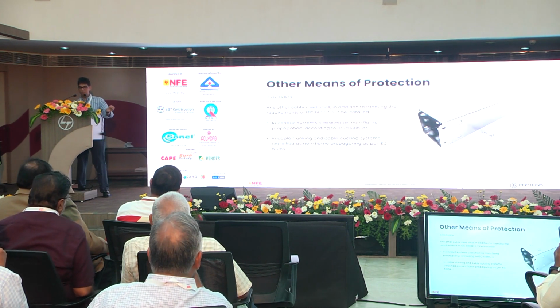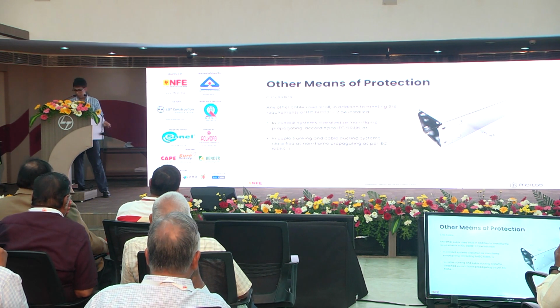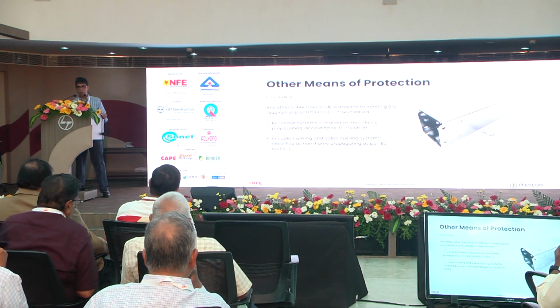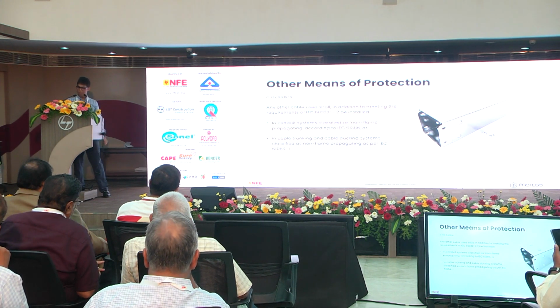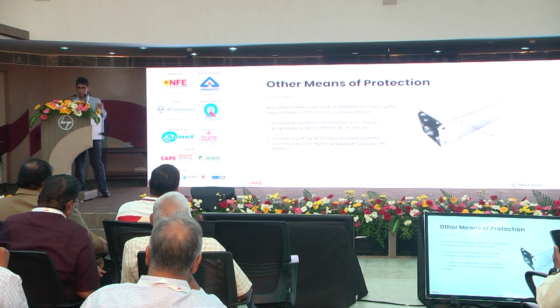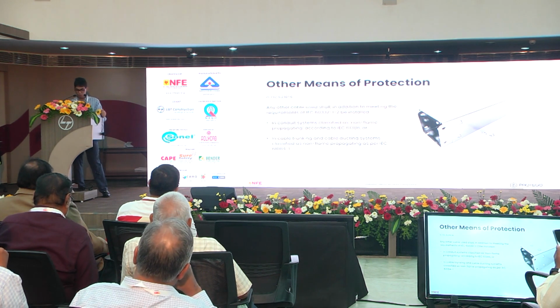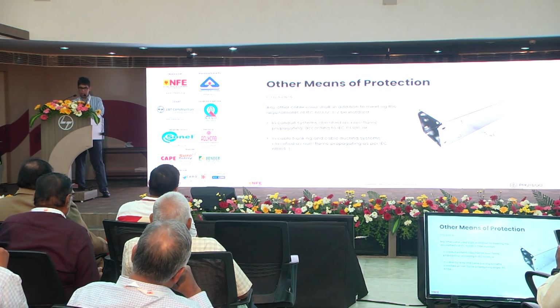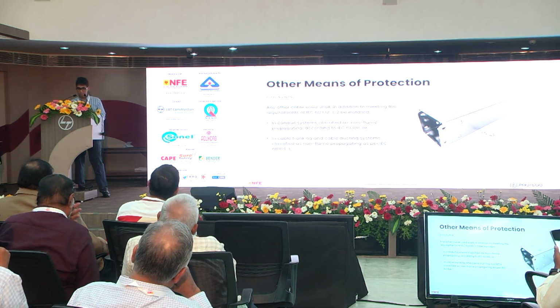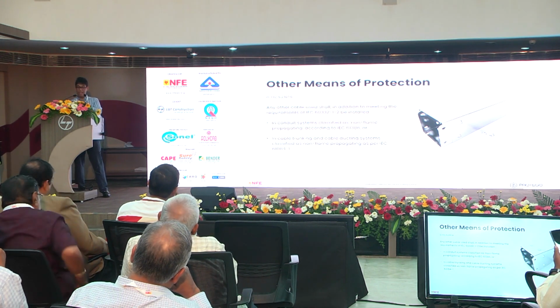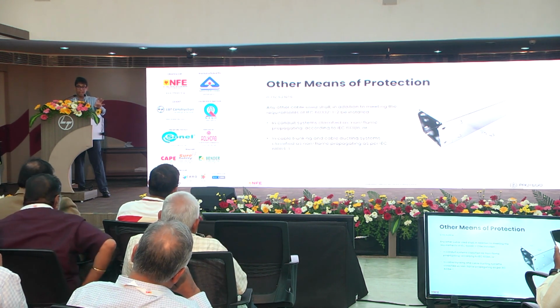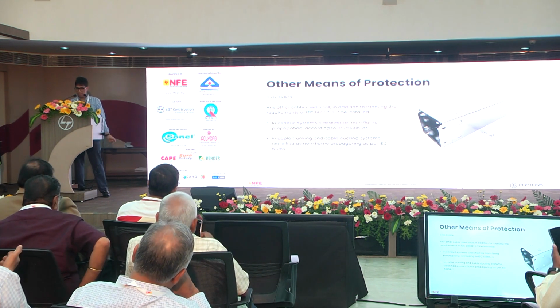Additionally, if cables are not fire rated or fire performance, a simple flame propagation test can be performed. If the cables comply with the requirements of the vertical flame propagation test, you can simply put the cable in a non-flame propagating enclosure, such as trunking or conduit. Remember, again, it has to be made of non-flame propagating material as per the relevant manufacturing standard.